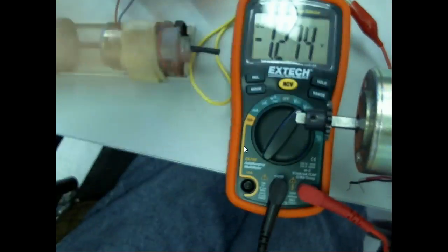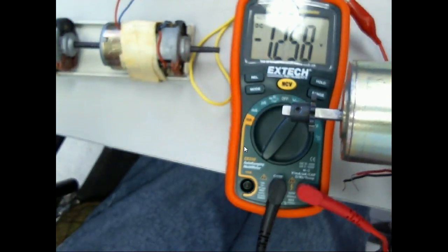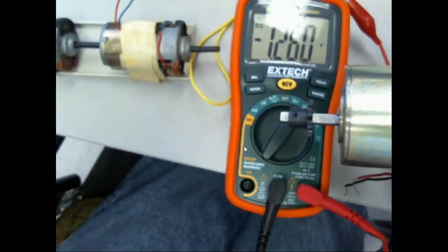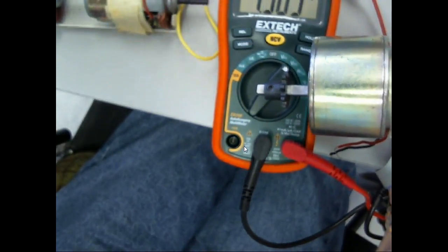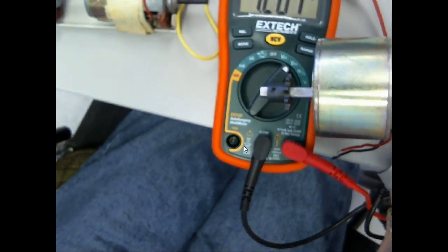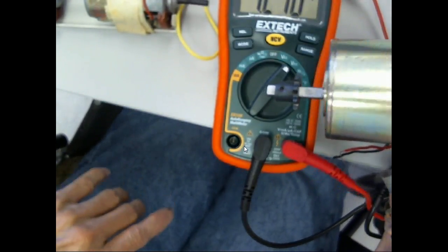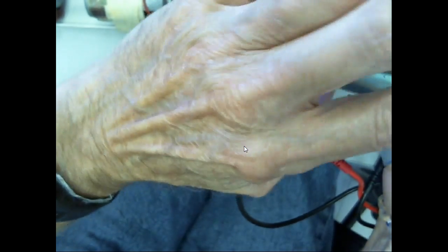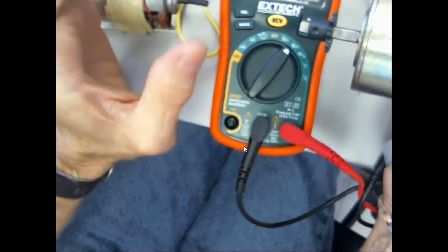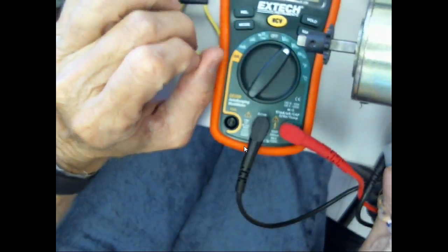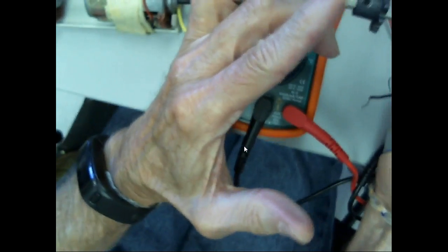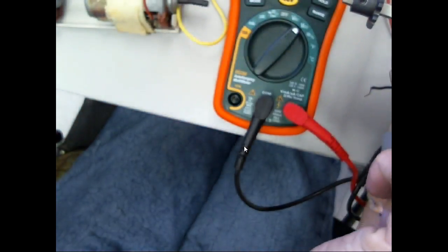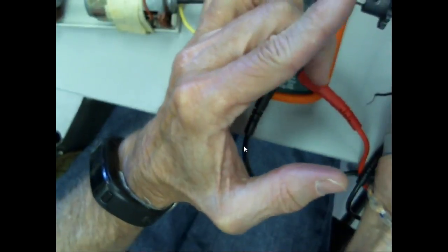And then if you take this and run it through a set of chain drives, which is what this robot did, you'd have to know the ratio of the chain drives, and you'd have to figure out the entire transfer function to figure out how fast the robot moved, right? You understand that? So let's just stop right here. So 65.5, that's the ratio to 1. Most of the time it'll be to 1. This has 6 blades on it. What does this see? So how many times would this thing right here pulse for this guy right here to turn 1 revolution?